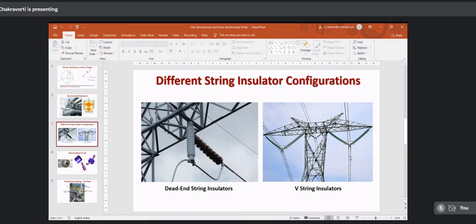This is a two conductor bundle. You can have a four conductor bundle. In India, two and four conductor bundle is very common, but you can also have 8 and 10 conductor bundle. The advantage is that each conductor is just like a normal conductor, so you don't require any special conductor, right? Because you have to always understand that you have to order these conductors and buy them. So if you order anything special, cost increases.